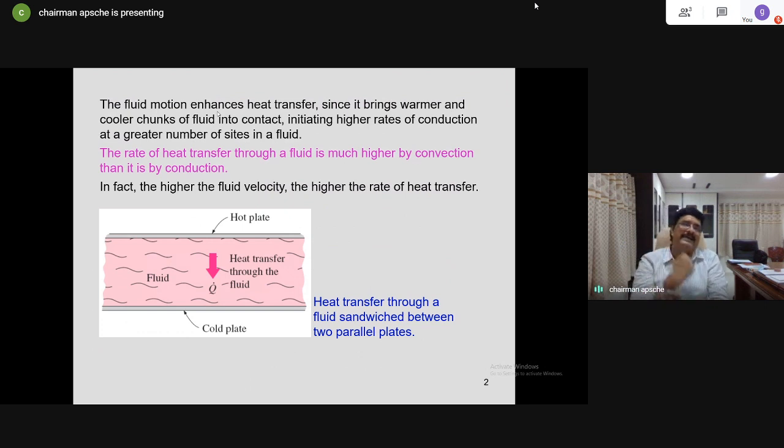When temperature is not increased considerably, quite naturally, the buoyancy forces will be minimum, because density is a function of temperature. See, I added 20 watts to this fluid, its temperature increases by say 5 degrees centigrade, so it is very quickly moving up because temperature is considerable. I added 20 watts to another fluid, its temperature has increased by only 1 degree centigrade. Its density is not increased as much, and therefore the buoyancy force experienced is lower. Again, density as a function of temperature.